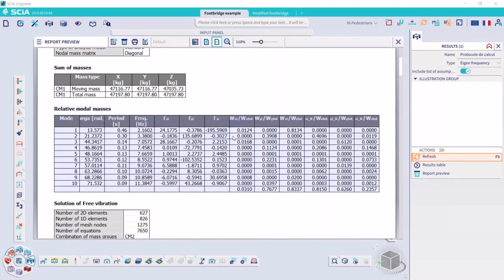And if we try to find a second mode which acts in the vertical direction, it will be mode number 9, which has a frequency of 10.86. Again, this falls in a range which is outside the critical range, so we will only consider the first mode.